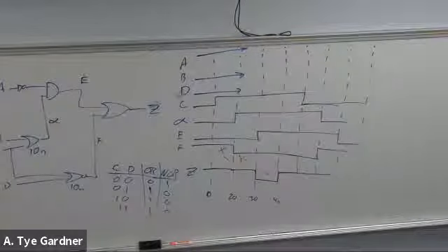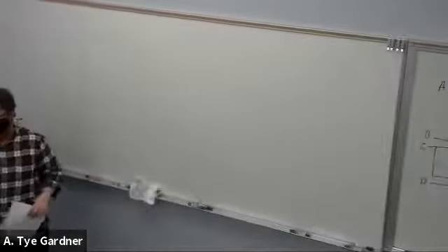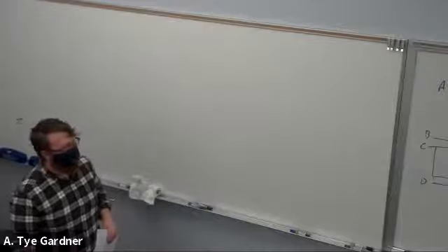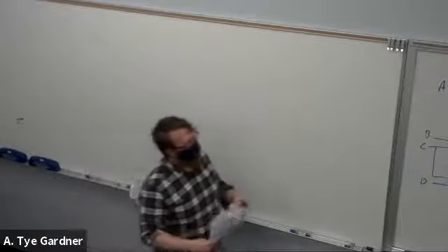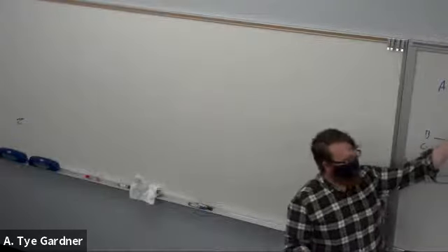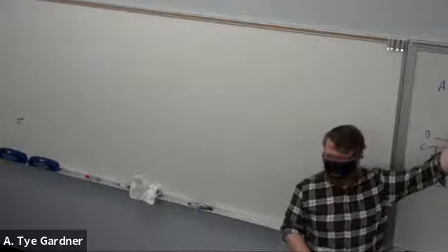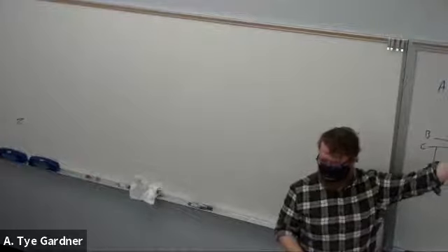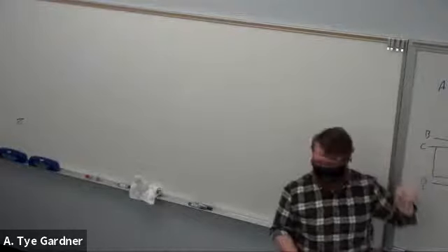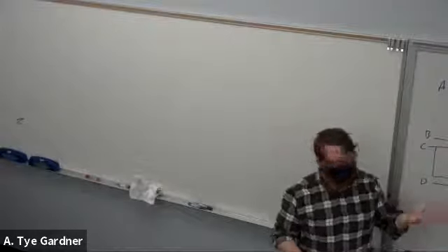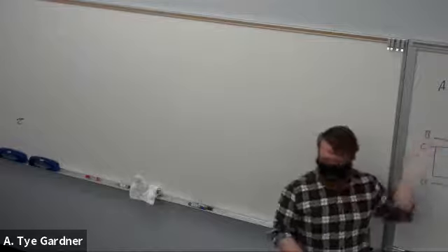I have a question. So we found a static hazard because Z was 0 and was supposed to be 1 the whole time. How did you know that it was supposed to be 1? That answer is actually pretty straightforward. It's because I can't prime the circuit to be 0 in response to this C. Any other way I prime this circuit, the C changing doesn't matter.